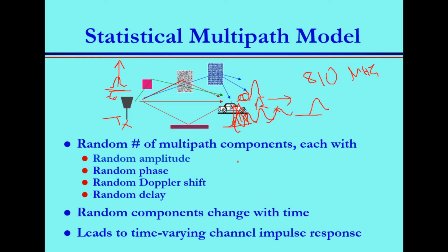Phi n represents the random phase. And phi also has the Doppler information, because Doppler depends on the angle of arrival of your received signal, with which direction you receive it. For example, when you are moving in a street, everybody knows that the police uses radar to detect if someone exceeds the speed limit. Is that true?